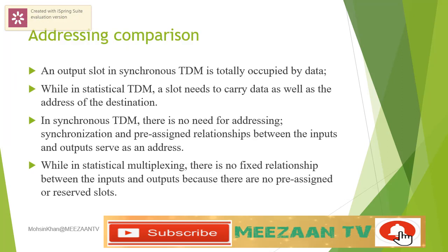The output slot in synchronous TDM is totally occupied by data. In synchronous TDM, there is no need for addressing. Synchronization and pre-assigned relationships between the inputs and outputs serve as an address. While in statistical TDM, a slot needs to carry data as well as the address of the destination. Furthermore, there is no fixed relationship between the inputs and outputs, because there are no pre-assigned or reserved slots.